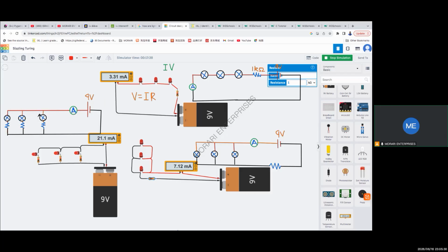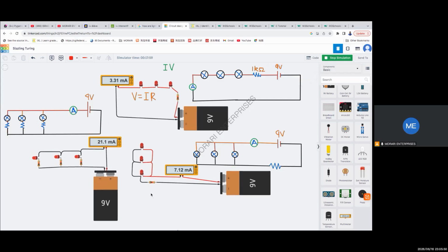And now, each LED got its own resistance. And then you see here, this LED resistor here, this LED resistor here, this LED resistor, as in this circuit, right? And now what do we need to do? Okay, so what do we need to do here? We see that it's much brighter and the current is 21.1 milliamperes. It's actually above the 20. So drastically it has increased the wattage, because we have to take this and multiply it by the two.